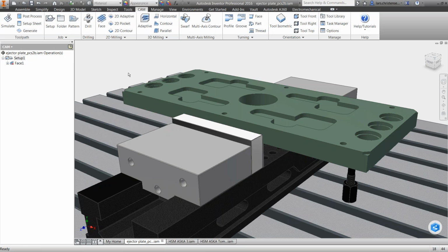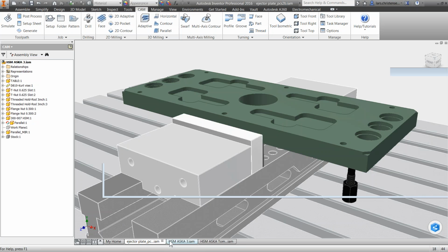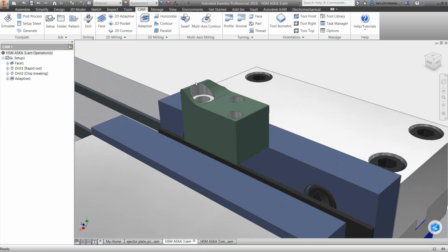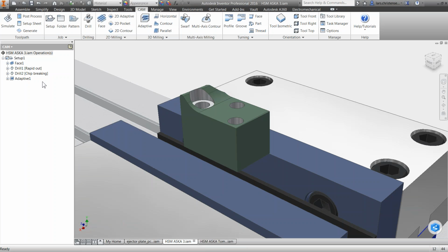We also do have 3-axis, and I just wanted to quickly give you a little idea about that, because that's one of the things that I used to do quite a bit. And actually, using CAM, I have had a little bit of trouble when you get into what is called 3-axis swoopy surfaces. So here I have another part sitting in another vise, another brand of vise, doesn't really matter. But what I've done to this little part here is that I've already programmed a little facing operation. I've already drilled some holes, and then I have already machined around it to rough it out.